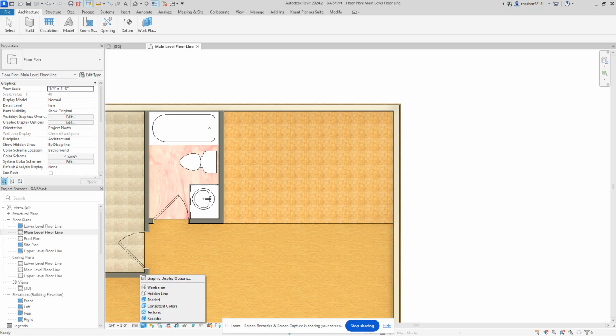How do I get rid of these old wall lines? The yellow ones? Oh, is that the AutoCAD sketch? Probably. You have 2 choices. You can go up here and hide it, so it's just there for the future, or you can delete it. It doesn't have to be deleted. So just hide that whole element. It's gone. Always choices.